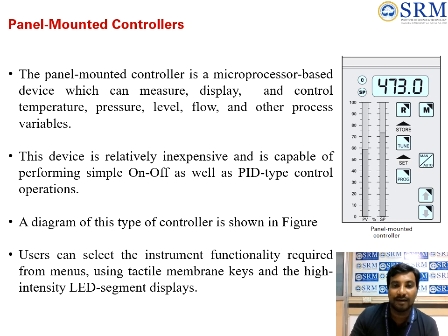By pressing the M button, several modes of operation can be accessed such as on-off parameters, PID gain settings, and preset limits that activate an alarm when they are exceeded. The specific value for each mode is shown on the digital display as it is programmed by pressing the up and down arrows after the programming key is pressed. The bar graph also indicates the set point value selected and the runtime status of the process variable that is being controlled.